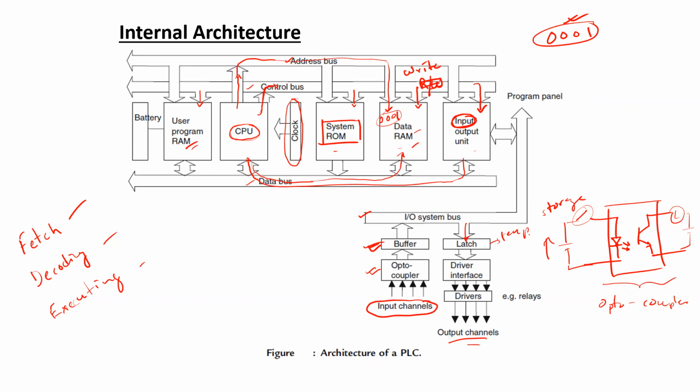There is the option to connect multiple PLCs using the Ethernet port, and make some sort of a local area network. So yes, you can transfer data obtained from one PLC to another PLC. That can be used to actuate some process in the other PLC. In that sense, you can influence the operation of one PLC from the data obtained from another one.